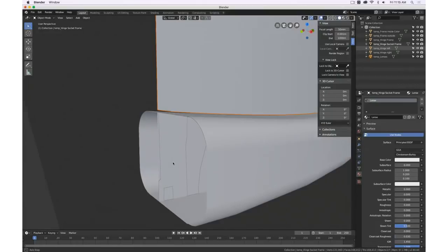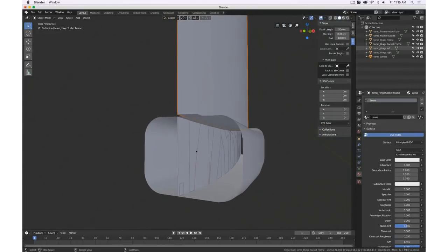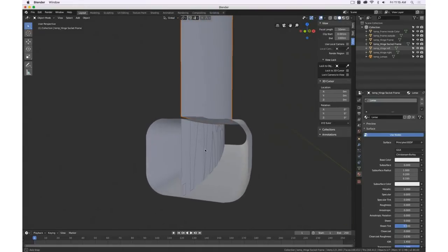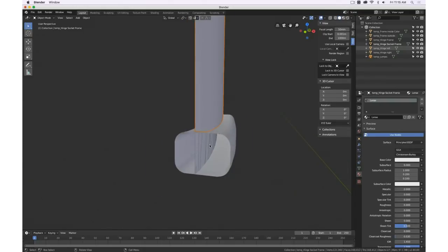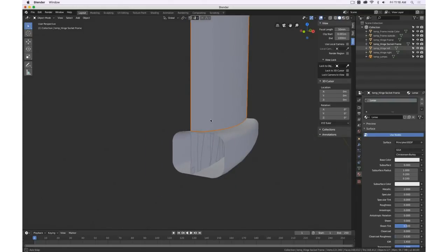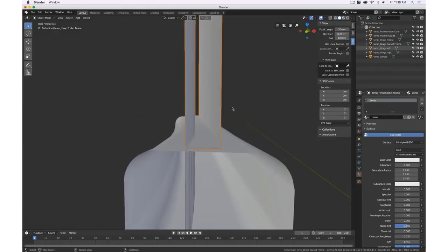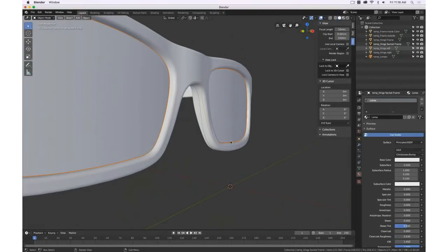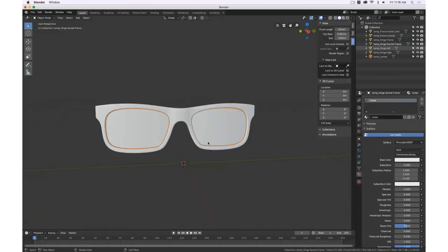But as you can see in here, in CAD, objects are never next to each other. They're perfectly intersecting each other, just one surface and the other surface. And in the rendering of the frame, that doesn't really show up. But with the glass, when looking through the lens, we would be able to see how this lower part of the lens would intersect with the frame material, which is why in Shaper, I made the lens just a tiny bit smaller. Enough so you don't see it, and enough also I don't get that render height effect.